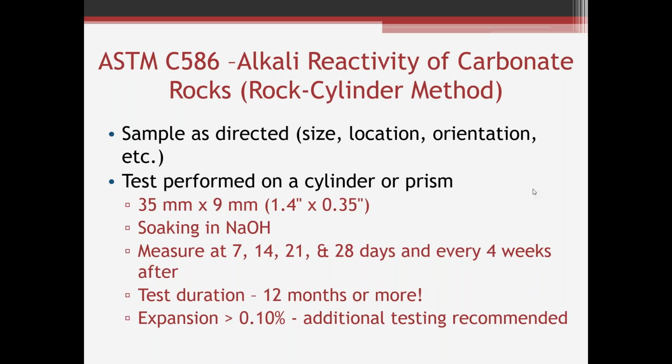But we're looking for the same thing. We're looking for that expansion. That expansion is caused by the reaction. So we know if things are expanding as they're exposed to the alkalis, sodium hydroxide in particular, that there's some kind of reaction going on that is probably not going to be welcomed in our concrete. It's going to be detrimental to our concrete. But again, this one's a 12-month test also. This is done on a cylinder. It's not done on a crushed piece of aggregate.